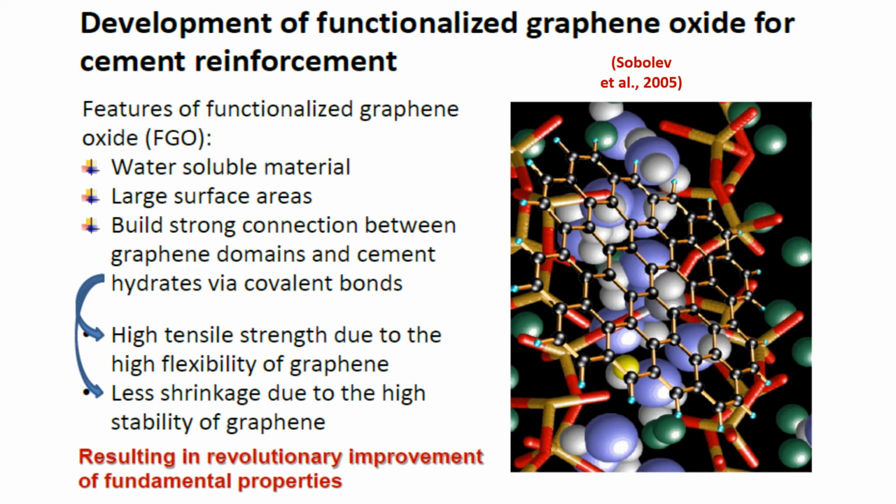What I understand from the term FGO, or functionalized graphene oxide, that this group mentioned or used, is some kind of engineered graphene oxide. So I think they synthesized graphene oxide and further functionalized it, or they somehow modified the Hummers method to have their unique functionalizations on the graphene oxide surface, so that it will be compatible in terms of chemical interaction. Compatible means that it is able to interact with the different chemical components present in the cement or concrete material.